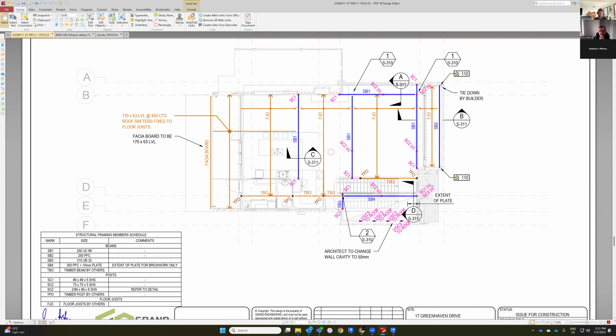I tend to think you should be able to put a few more studs in there and have the beams hang off that. But the other thing to look at is potentially using LVLs instead of steel. I think the span's too big, it's about 3.5. And the other problem, I think why it was a problem in the past is because we've got a big tube of that living room, there's not much bracing happening.